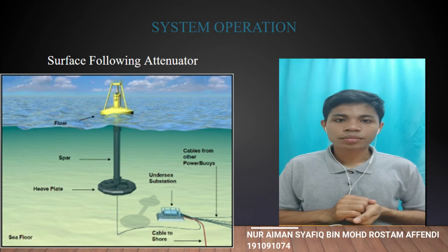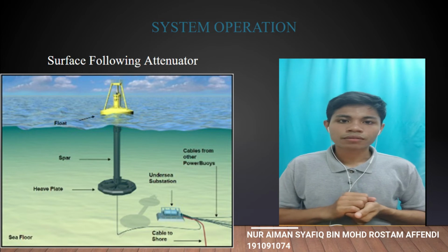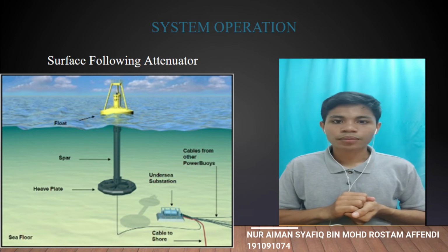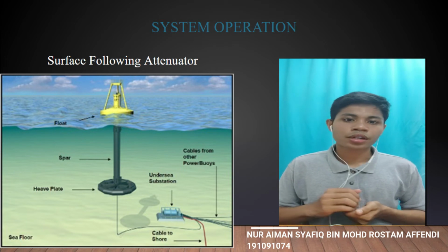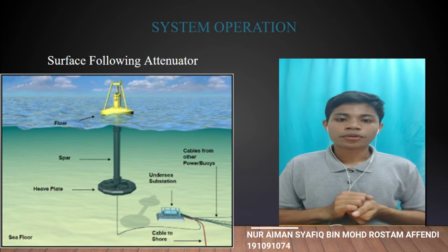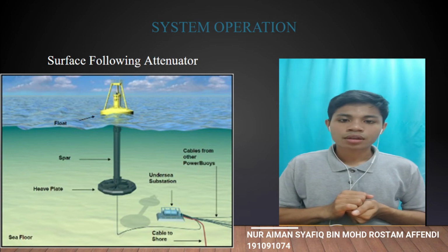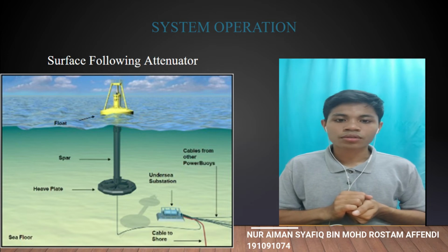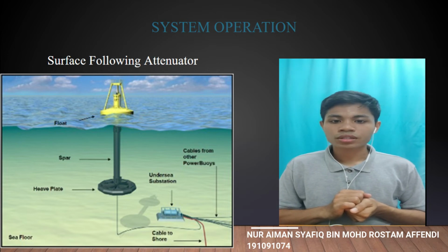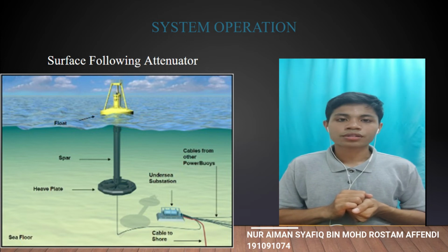The Azura station makes use of floating surface technology that absorbs energy from waves coming from all directions, and the generator is powered by a high pressure hydraulic system. The wave motion is captured by the floating mechanism's circular rotation, which is then transferred to Azura's crankshaft. This crankshaft provides motion for the high pressure hydraulic system.